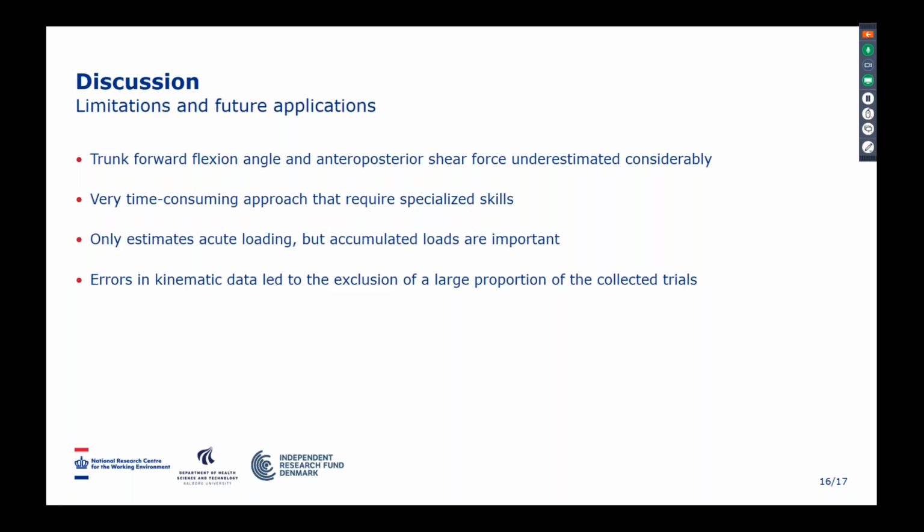One thing to mention is that the placement of the IMU on the XSens system is a little bit tricky, because you put it just over the sacrum on the pelvis with a band you attach around the subject, and it has a tendency to move around a lot, especially when you bend forward and lift something. So if other people try to use this for analyzing lifting, be aware that you need to continuously correct where the pelvis IMU is placed.